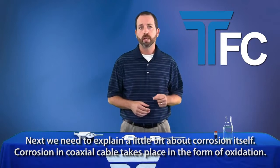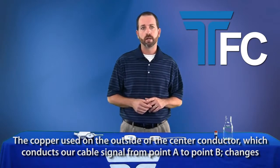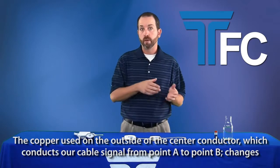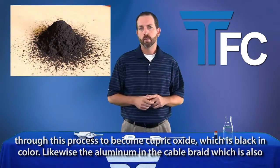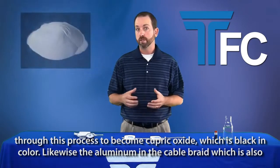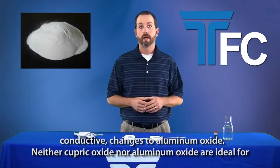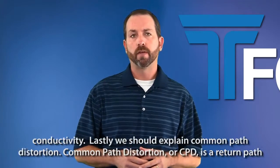Corrosion in coaxial cable takes place in the form of oxidation. The copper used on the outside of the center conductor, which conducts our cable signal from point A to point B, changes through this process to become cupric oxide, which is black in color. Likewise, the aluminum in the cable braid, which is also conductive, changes to aluminum oxide. Neither cupric oxide or aluminum oxide are ideal for conductivity.